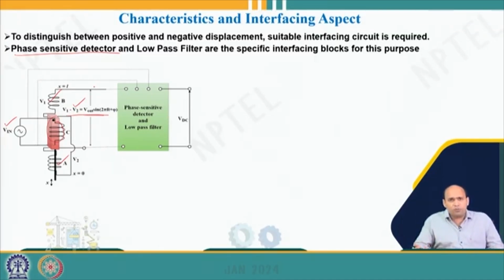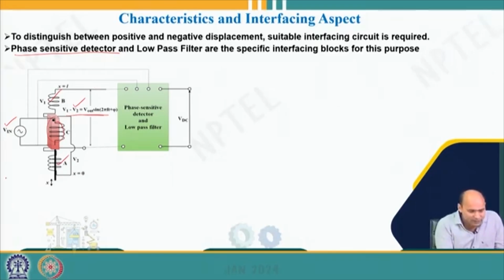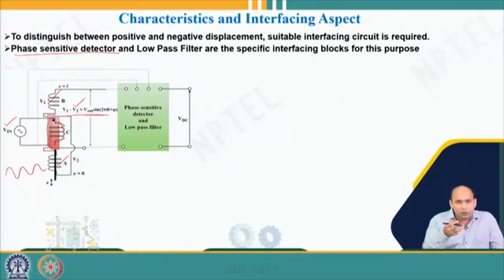So if I look at any AC waveform in some oscilloscope or some waveform measurement device, then you cannot distinguish by looking only at the waveform, you cannot understand what is the phase, right? Because in both cases it will look like this kind of sinusoidal thing, isn't it? In order to distinguish the phase, you have to compare two signals, then you can understand. But by looking at only one waveform, you cannot tell whether this is in phase or out of phase.